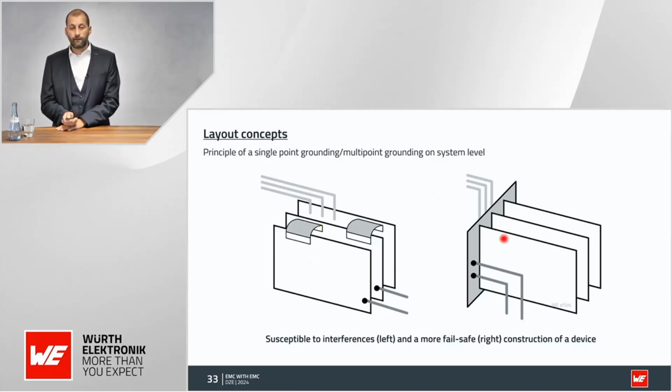In the better case, if we have some problems on the cable, due to the ground plane it will hopefully go the direct way out of your system. So star topologies are really good and really useful. The same goes for separating analog and digital parts on your circuit board.